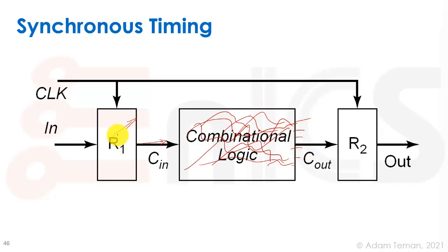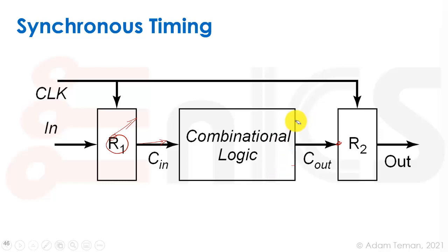And eventually you can always mark a certain register, a single bit out of this whole bus, a path that goes through all kinds of gates and comes out and gets to a single bit. So for each path, you can find what the start point and the end point is pretty straightforwardly and easily. And so you can model our whole circuit as a bunch of these sequential paths from a single start point to a single end point through a combination of gates. That is how we look at the world. We look at all of our sequential system as a big collection of these circuits that start with a launching register, go through some combinational logic, and arrive at the end at an output register, a capture register.